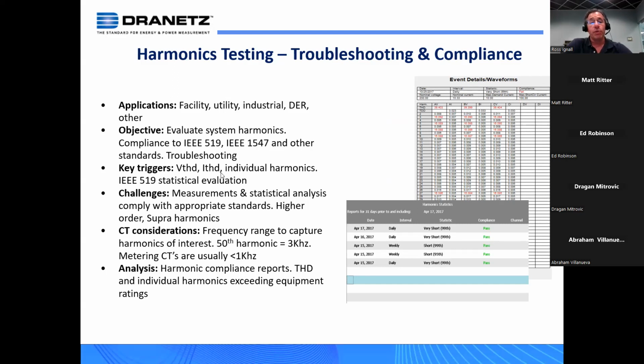Or maybe you're just troubleshooting. You have a harmonic problem. You think something is tripping off, so you're just looking for basic VTHD. The key triggers: THD, ITHD, individual harmonics, and the statistical evaluation by IEEE 519 2014 and higher.